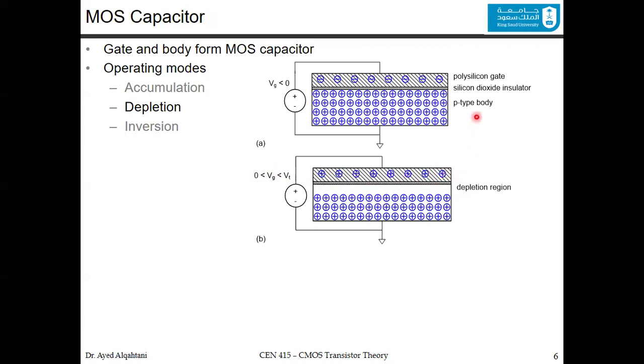If you compare it to the previous case, there was a negative charge since you didn't apply any voltage. So the negative charge is more than the positive. Now you applied more positive charges because you have voltage larger than 0 in the gate. So you have these plus charges, or you can actually have more positive than the negative in the polysilicon gate region.